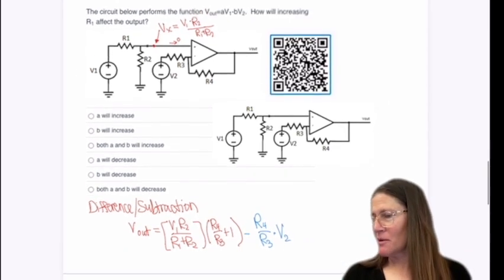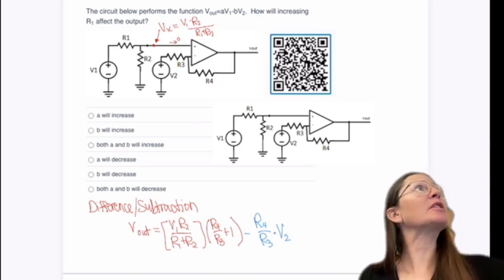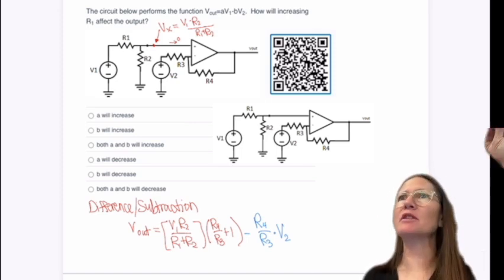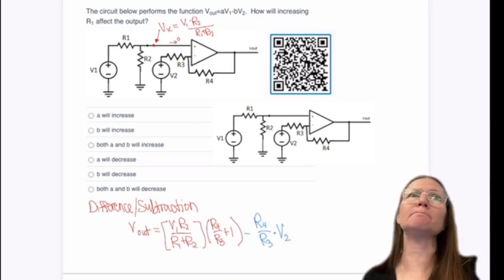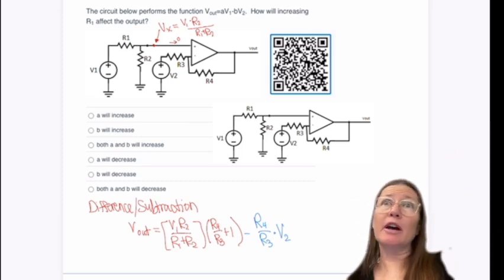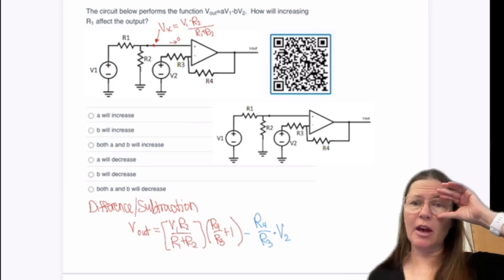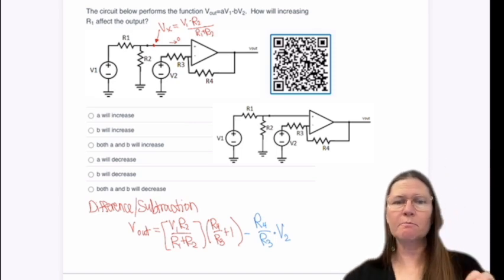All right, good job. So identifying this, you see it has two inputs, V1 and V2, one on each positive and negative, so a different subtracting configuration. So with that, then you say, okay, the equation, you can go back, look at the graph of it, or the table, and get that equation.